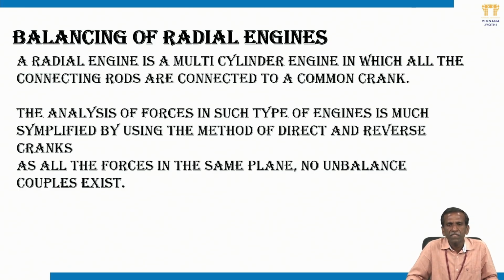The analysis of forces in this type of engine is much simplified, and complete balance is possible. We are going to analyze it using the method of direct and reverse cranks. All the forces are in the same plane, so no unbalanced couples exist.